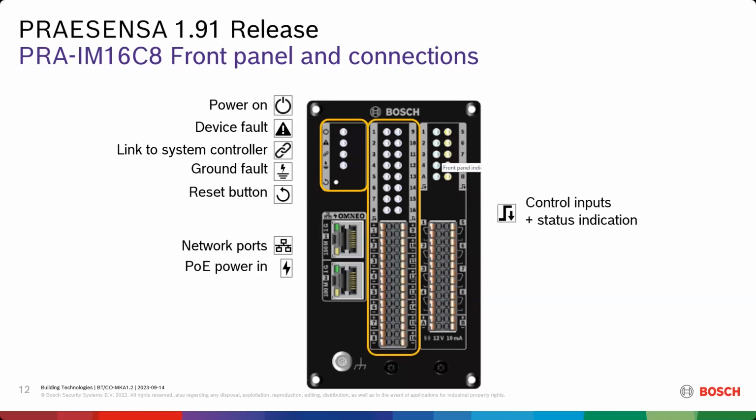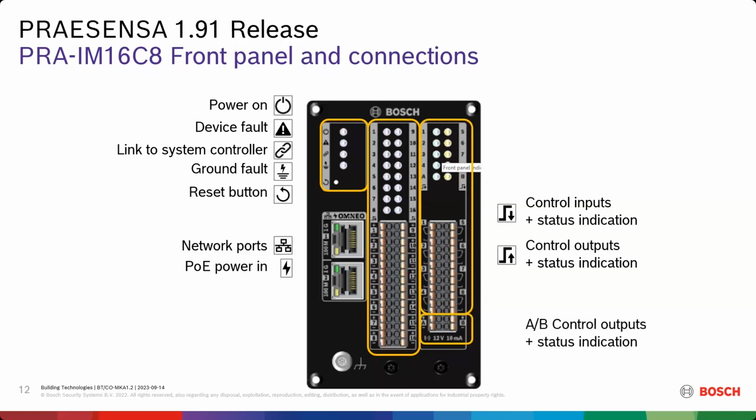And you have then in the middle the control inputs, so the 16 control inputs with a status indicator. Unlike the MPS, which is not really showing the actual status of these control inputs, this I/O module does provide us with these LEDs. And then you have the control outputs, where you have your 8 control outputs and your A and B monitored output, with also a status indication if that control is activated or not.